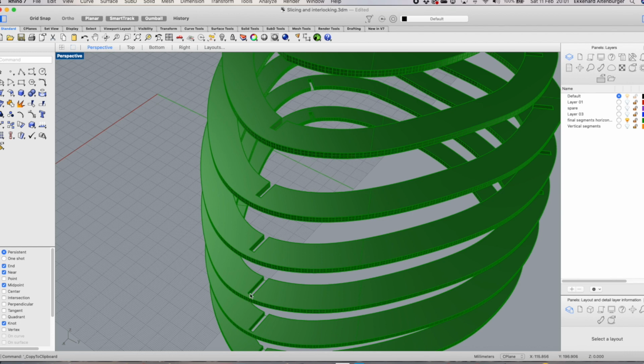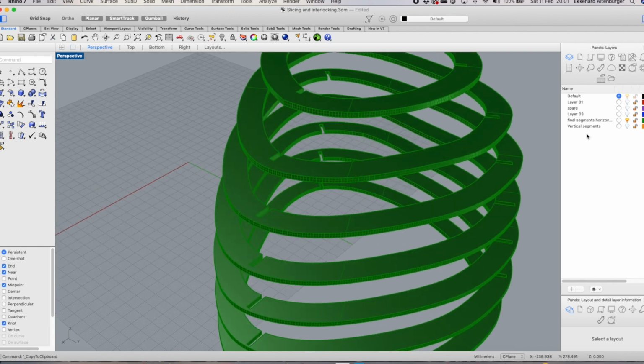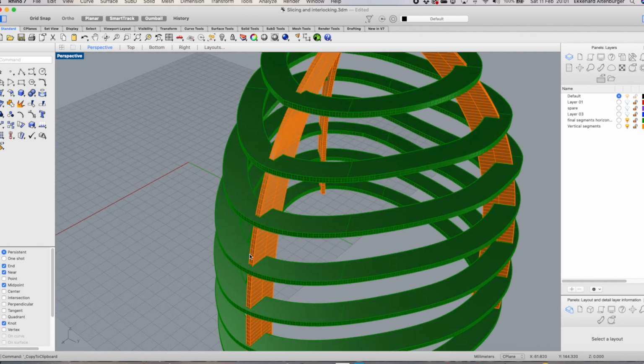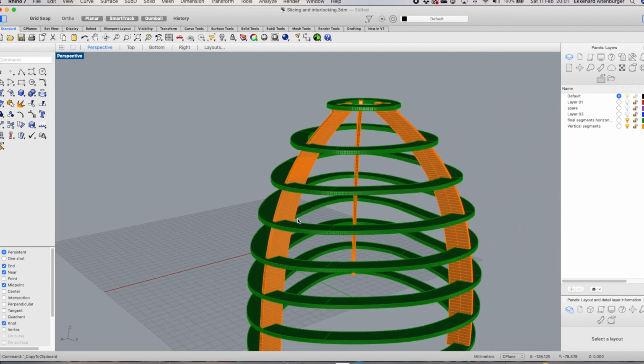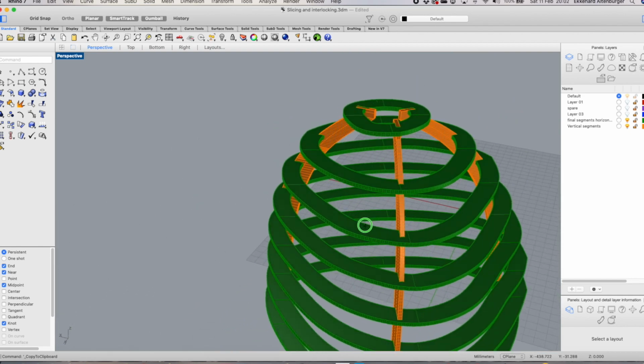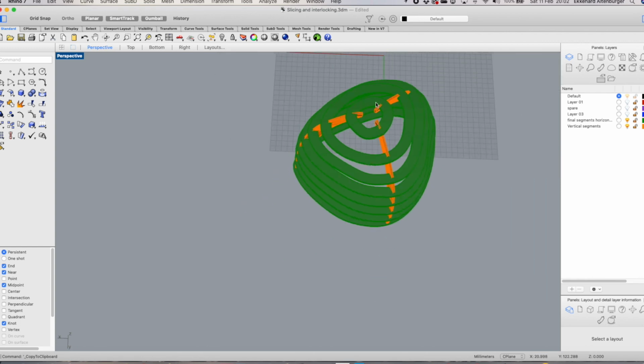Basically what I show you is, I intersected these ones, and you need to move a little bit in from the outside, otherwise you cut through your rims. So you need to move the mesh edge inwards and then extrude it. I show you a slightly easier way to do this, and do not do it in a triangle. Although this looks nice, I do not recommend this. Just make four cuts through your object. That's easier, because you need to rotate this constantly to line it up and make it work.